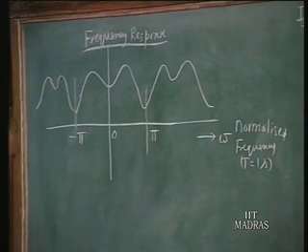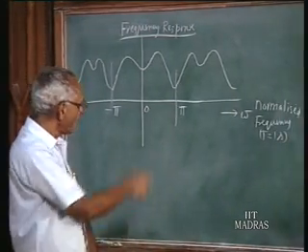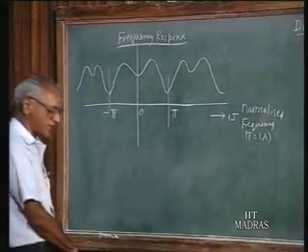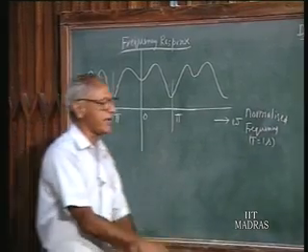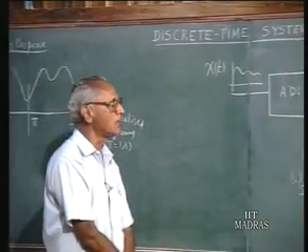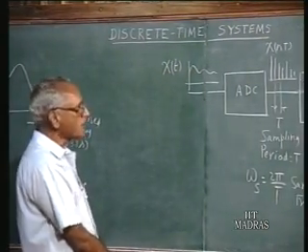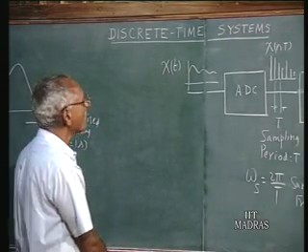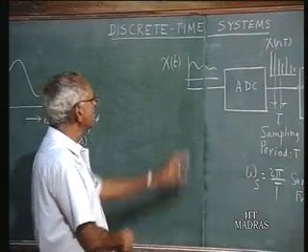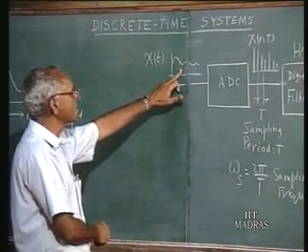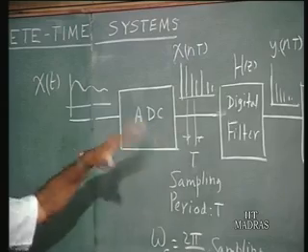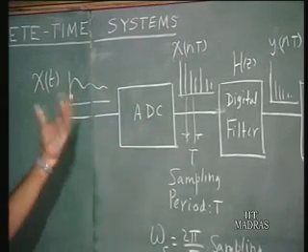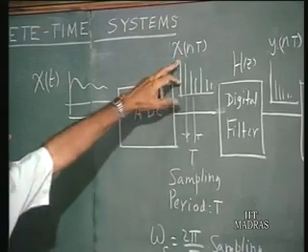Now, I mentioned that we have taken here the normalized frequency, that means the sampling period is equal to 1 second. Let us look at a general case where discrete time systems are commonly used. A digital filter gives a particular example of a discrete time system. In a digital filter, what is done is a given analog signal, continuous time signal x of t is digitized, is discretized, you generate from this through a sample and hold circuitry and analog to digital converter and whatever it is, x of n T.